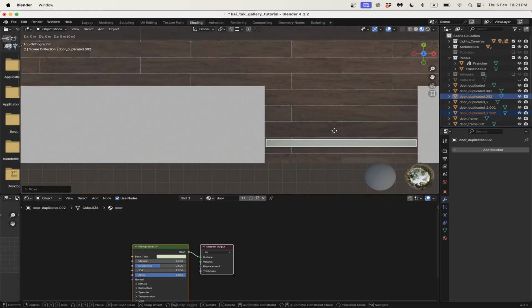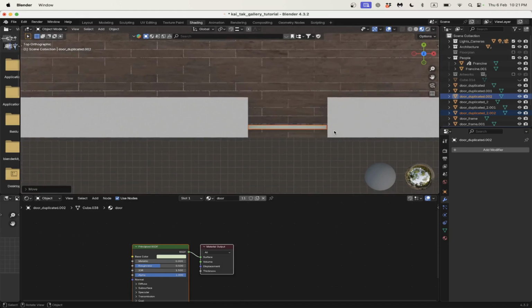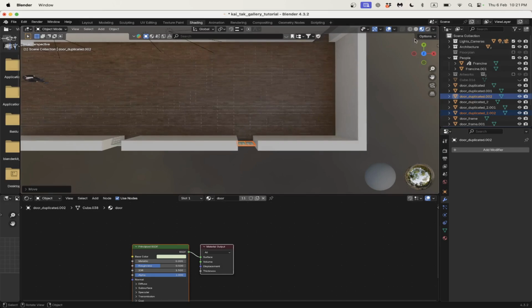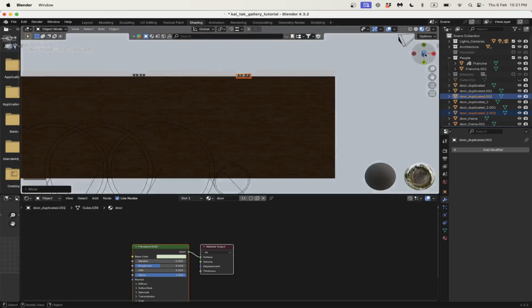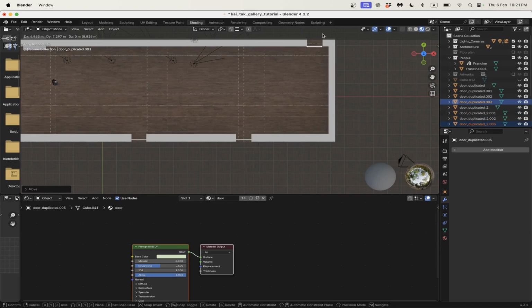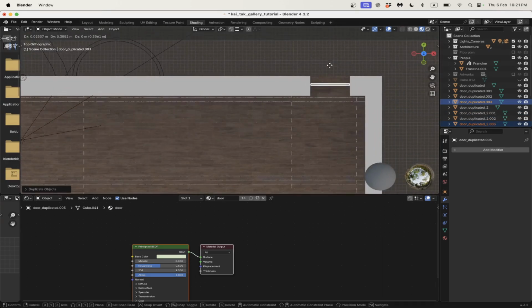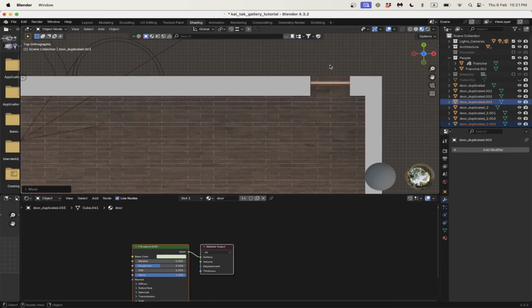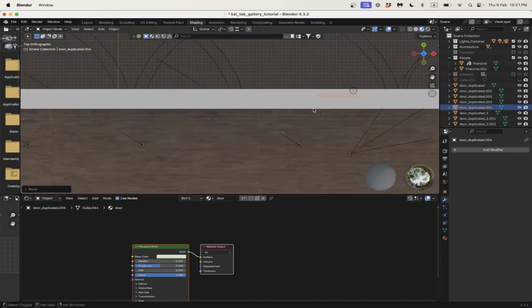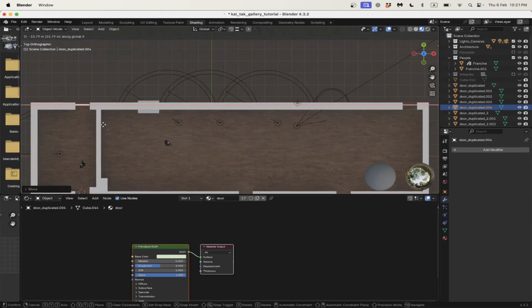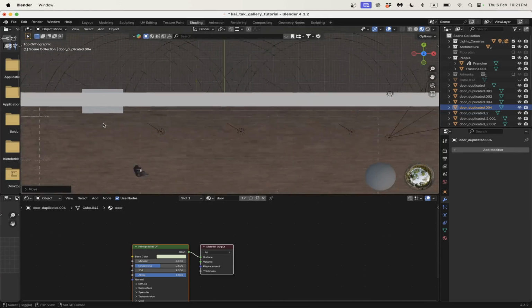And that door frame's a little bigger. It could also be just me being a little inaccurate when I was looking at the doors from the floor plan. Okay, so let's look from the top again, and Shift D, and I'm going to move on to the other side and pop that into place there. Shift D, GX, and I'll press Shift and middle mouse to pan my view, zoom out a little bit, GX, and we'll get the final doorway.